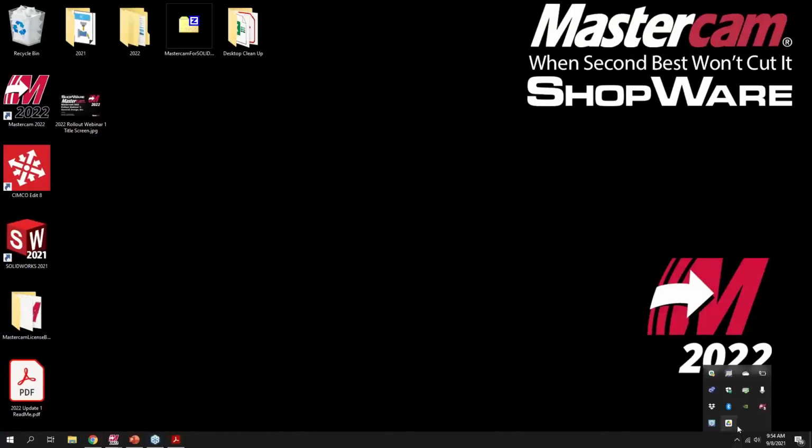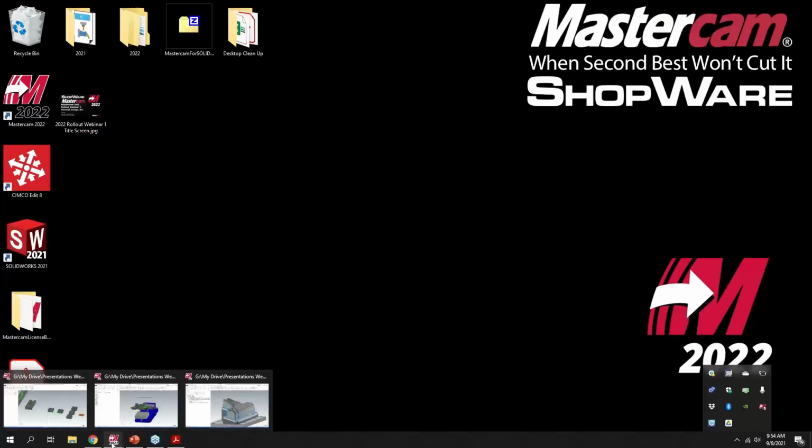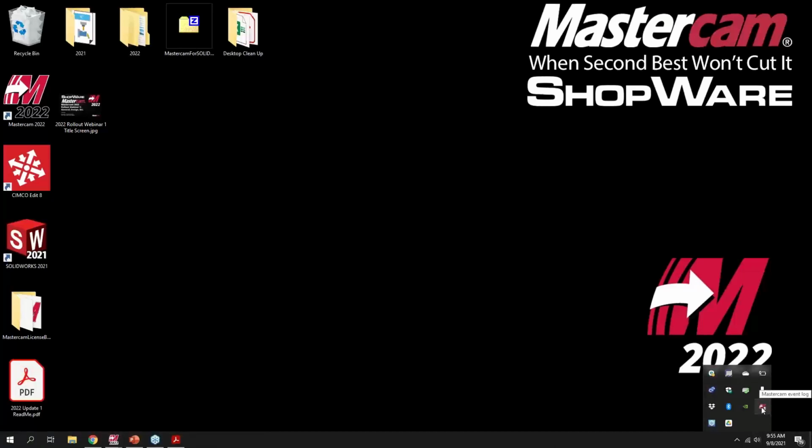So Mastercam should automatically pop up. I actually closed out of it, but when you go to fire up Mastercam today, you might have already noticed the notification saying that there's an update available. One tip there is that app is actually separate from the main Mastercam executable. So if you close out Mastercam first and then run through the updater, you won't have to reboot your computer. So you can save yourself a little bit of time. But make sure Mastercam has time to fully close out and that the Mastercam event log is also closed out. Then as long as both of those are closed out, like I said, you can update to update 1 and be on your way.